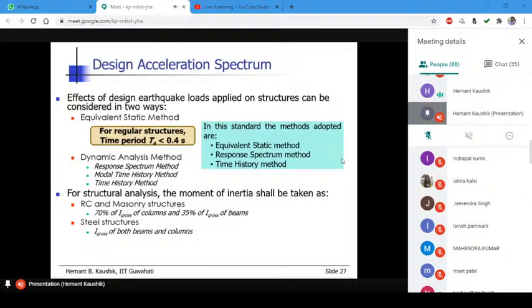So for every mode, for that modal period, the software computes the maximum response SA by G from the design spectrum which is given as input to the software. So let us say there are 10 modes of vibration, it will compute 10 SA by G values, find out the base shear, and then it somehow combines all these responses of single degree of freedom systems to get the final response. This is the response spectrum method.